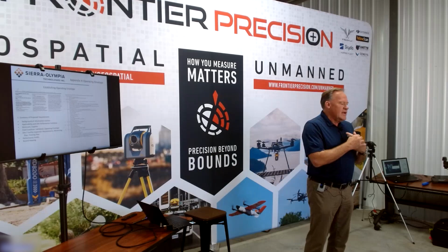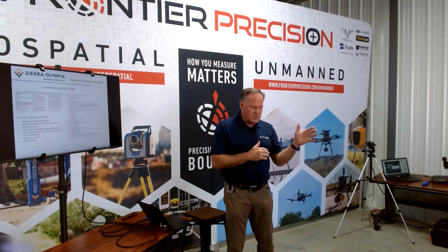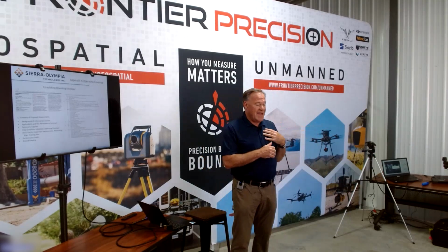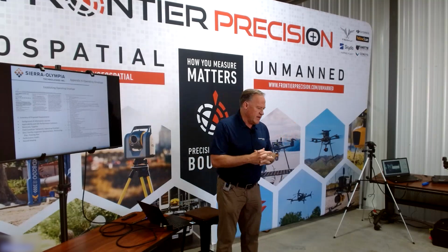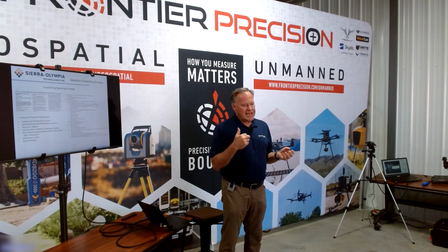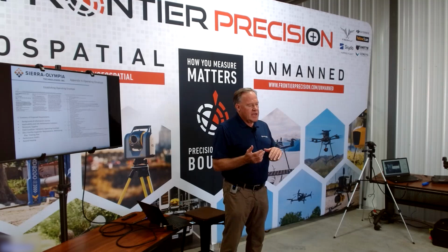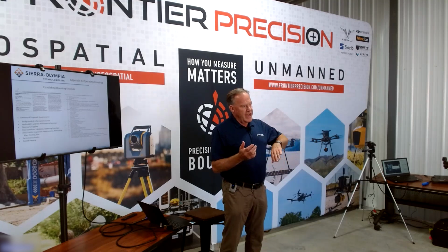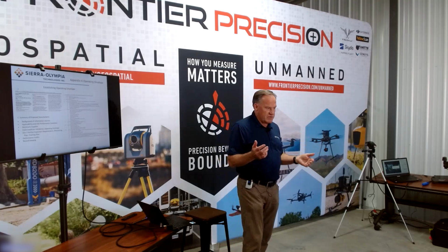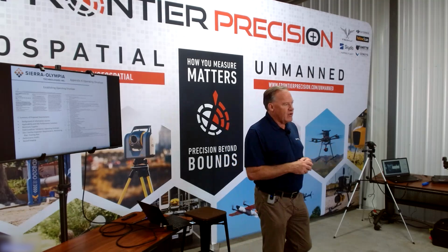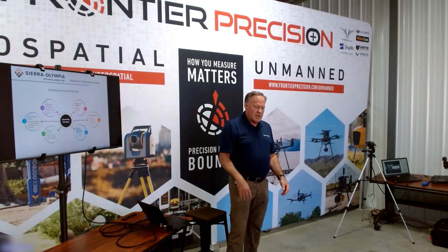In Appendix K, they're now calling out that either the end user, the operator, the manufacturer, like us, or service companies, they would like people to now establish what is called the operating index and the operating envelope of when you're using an OGI camera, especially if you're going to use it as the alternate work practice to Method 21 of using sniffers. You actually have to validate how you're doing that. And what that looks like is something like this.